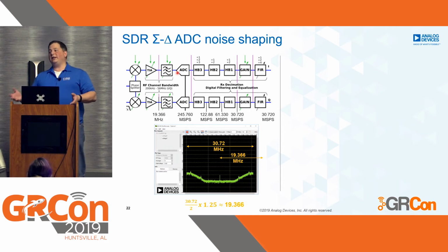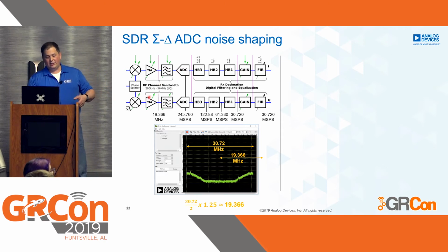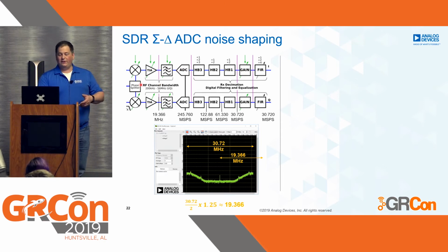So depending upon who's writing the data sheet, if it's the baseband guy, he'll talk about baseband bandwidth. If it's the RF guy, he'll talk about RF bandwidth. So when you look at data sheets and documentation, you'll see things like 56 megahertz. But when you program these filters, the most they go to is 28, because one is RF bandwidth and one is baseband bandwidth. It's half.